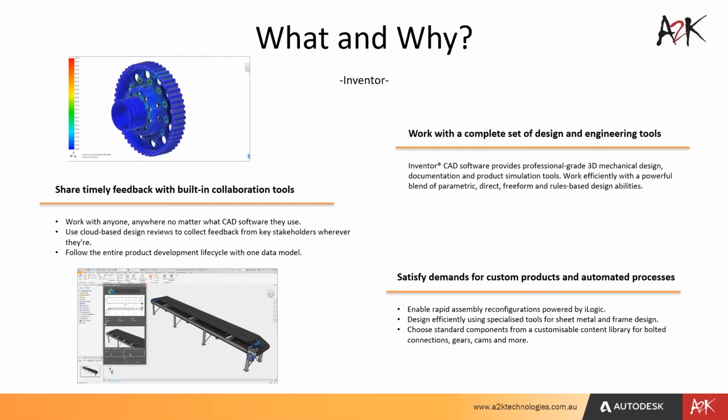It's got component generators and calculators to do things such as welds and clamps and press fits, tube and pipe, cable and harness. It's got the connected data for your printed circuit boards in Eagle, which is one of Autodesk's newer products. It's got the integration with Autodesk Vault, which we'll be talking about today, okay, which allows you to search from inside Inventor, you're searching Vault from inside of Inventor and quickly find, copy design, and connect to Vault.